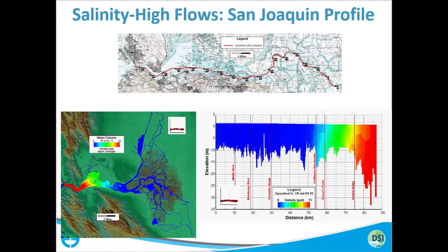So you can see again it's similar to the previous animation I showed, where the freshwater and saltwater interaction takes place. And this is the plan view, and this is the slice view. Both of them show the same thing. Here on the plan view, it's showing the depth averaged, because if you want to show all the layers, it would be 10 layers, or you can use the difference between particular layers you're interested in. So when you're reviewing the overall top view, it's better to see the depth average. And here you can see what's happening on each layer.